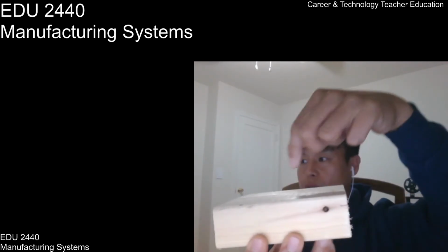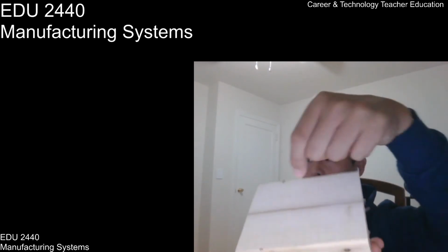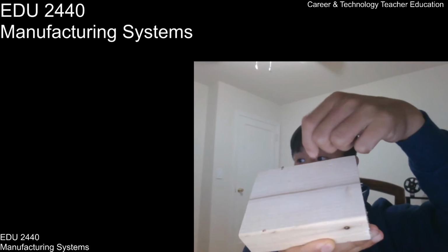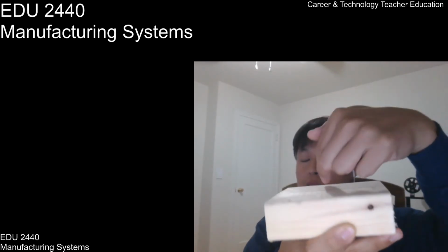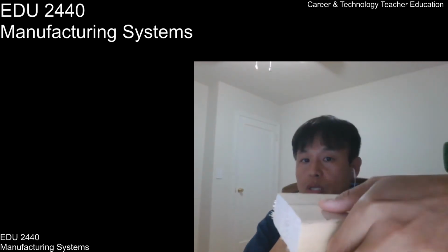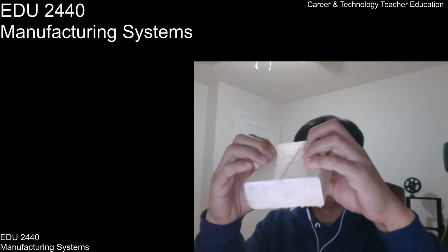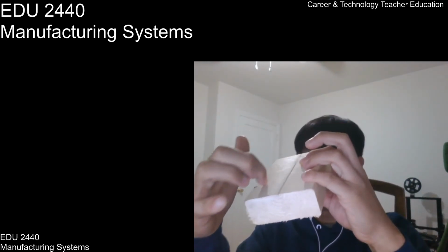Yeah, this way, because you see the fiber grain line. This fiber makes the wood stronger, right? So we need to use this across the grain line. That's stronger. If you try to make a certain structure using this direction, when we push more load, then the wood can be broken this way by following the grain line, right? That's important.